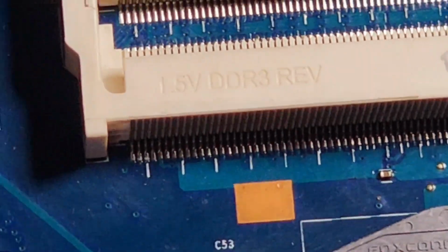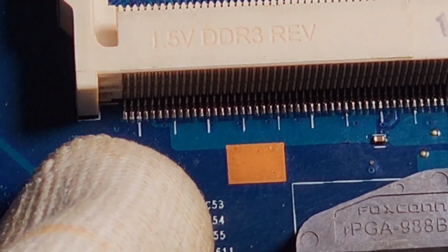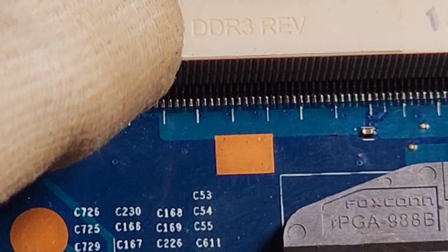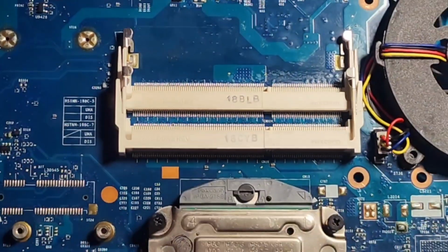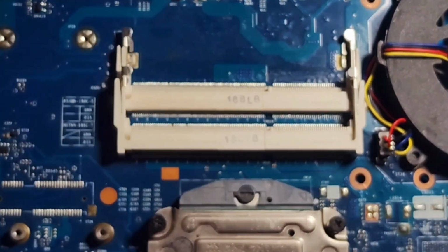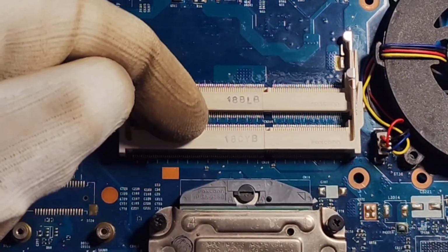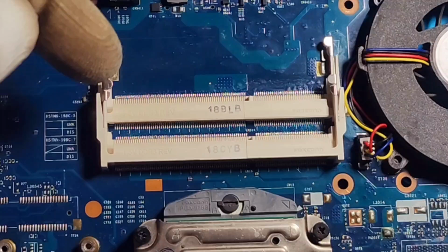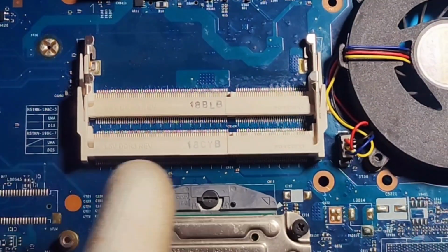So the system data and system clock lines are on pins 200 and 202 of this connector here, so we can check the system data and system clock also. I just found that when I connect the RAM in this slot and power on the board, I'm getting the same ampere. When I remove the RAM module from this socket and turn on the board, I'm getting the same ampere. Which means the RAM is not detected.